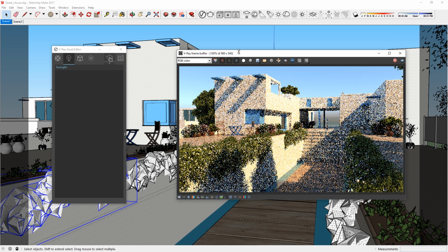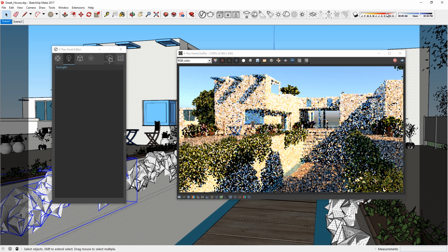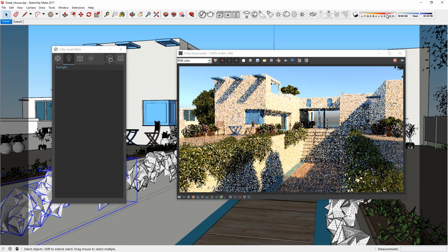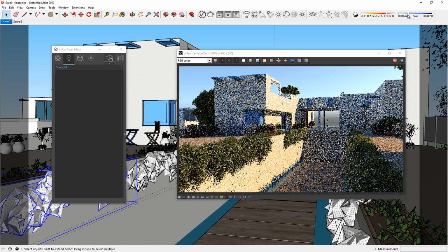And you can see we have the illumination coming only from the sun and the sky. The way we would move those is the same way we would move the sun in SketchUp, from the shadows panel. Here, in this particular scene, I've used the plugin called Solar North to change a little the axis of the sun, but besides this, we can control it from the shadows panel of SketchUp itself.